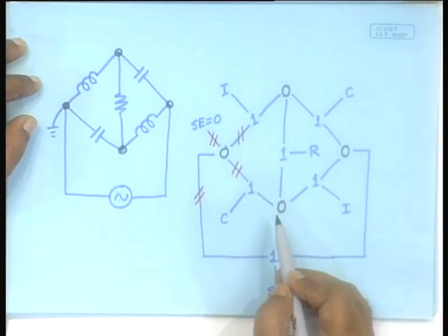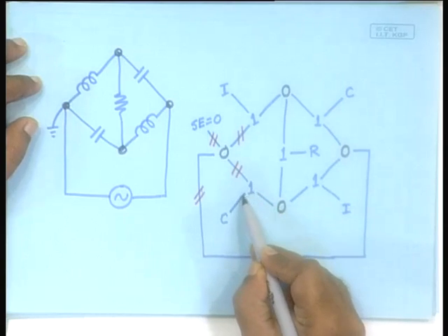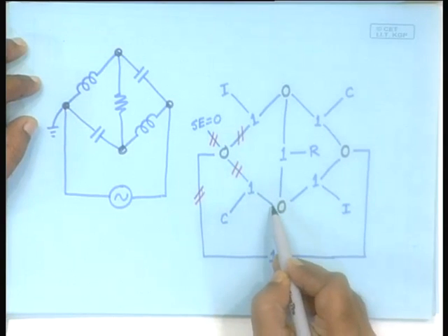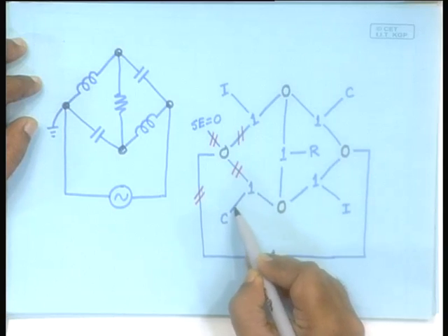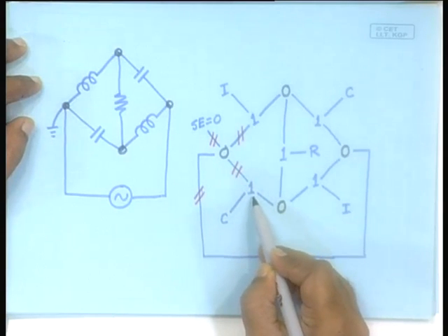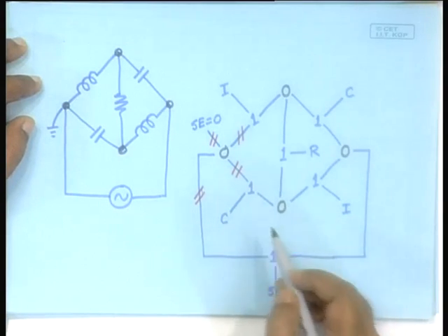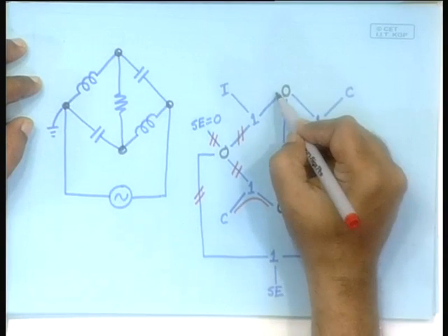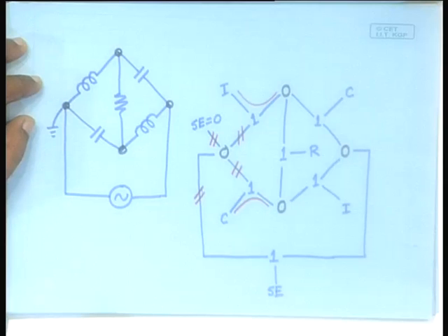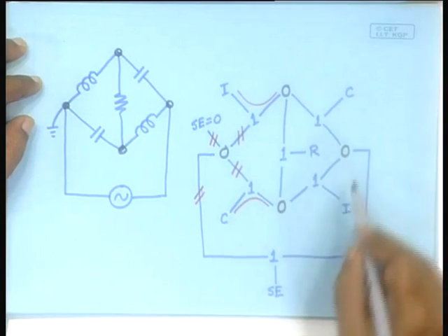Now, the moment you do that, you find that this becomes a through junction. So, whatever are the efforts and flows in this bond will be the same as the efforts and flows in this bond, and therefore, this one junction is unnecessary. So, we can then connect it through. Similarly, here through. Similarly, here this is not there, so this can be a direct connection.